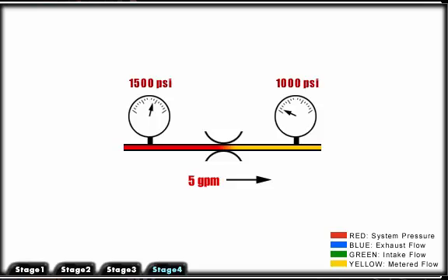The amount of flow through an orifice will remain constant as long as the pressure differential across the orifice does not change. When the pressure differential changes, the flow changes. Change in load or upstream pressure will change the pressure drop across the valve.